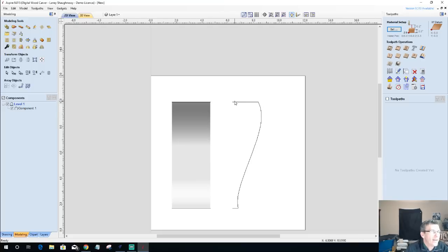Because I had my profile facing the wrong way or going backwards, it was recessing into that back side, cutting from the top down, the back down. And this part here, this bulge and all, is exceeding, and it was throwing everything off. It was kind of putting me under my Z-plane. It was causing errors and all.